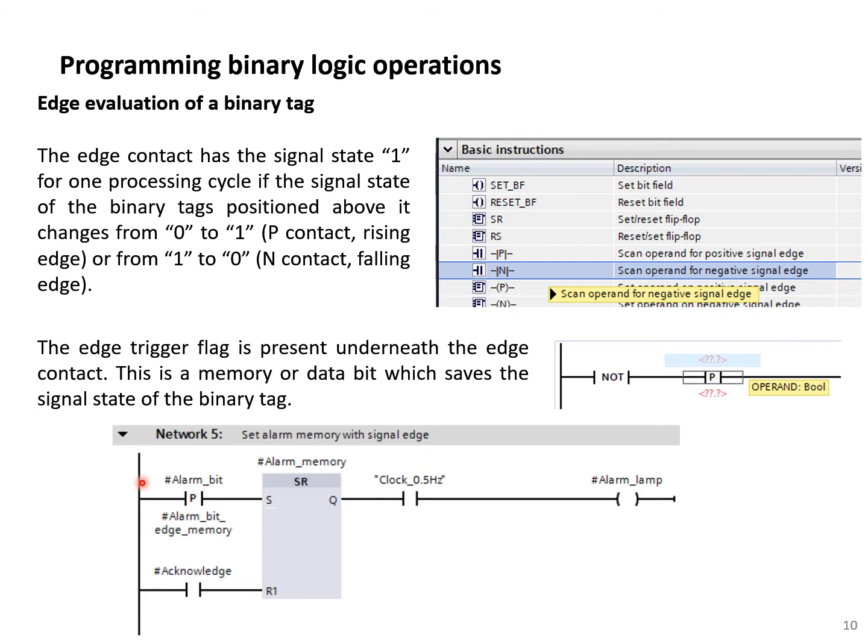Okay, so it could be, let's say, 1 millisecond, depending on the PLC scanning cycle frequency. Let's say for 1 millisecond, the contact will become true or false based on the type of P contact or N contact.